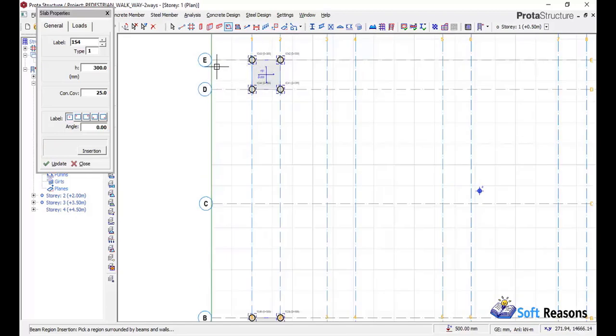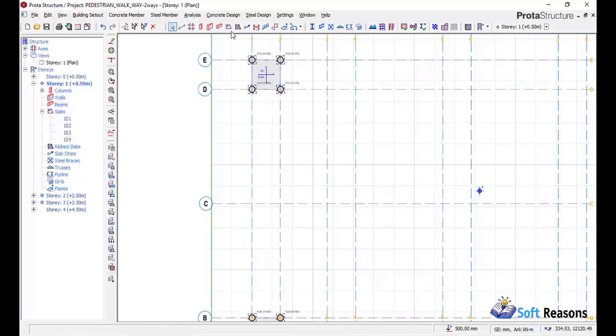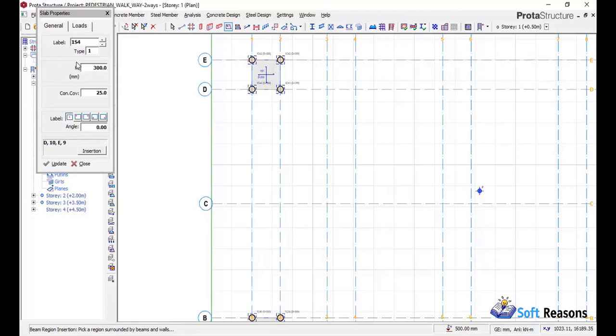Then the slab we are going to be having here is going to be a cantilever slab. Okay, now we take the pedestrians to the normal ground level. So click on close, close that dialog. Alright, activate the dialog again. Then for the cantilever slab here, we are going to click on this tab, right click inside of this type provision and then go straight away to slab type 12. Click right there. After which we'll be looking at the width of the slab. We consider 1200.